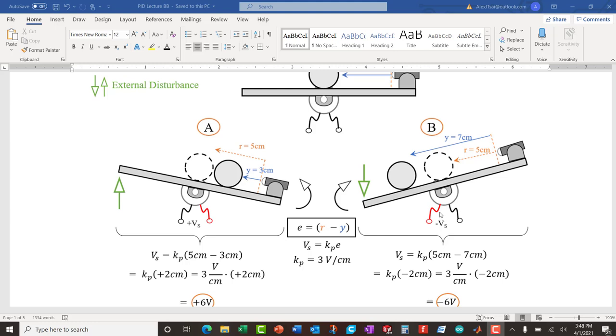If the polarity changes, well, for a DC motor, it simply means now we're spinning clockwise direction, and it wants to bring the ball back to the center. And that's essentially what proportional control is. It's just a way that we use the error signal to supply a voltage to the actuator, and it automatically makes the correction in the opposite direction of motion of, in this case, that ball. Okay. Now the question then is, what is the value of the gain that we must have in order to meet some customer specification?